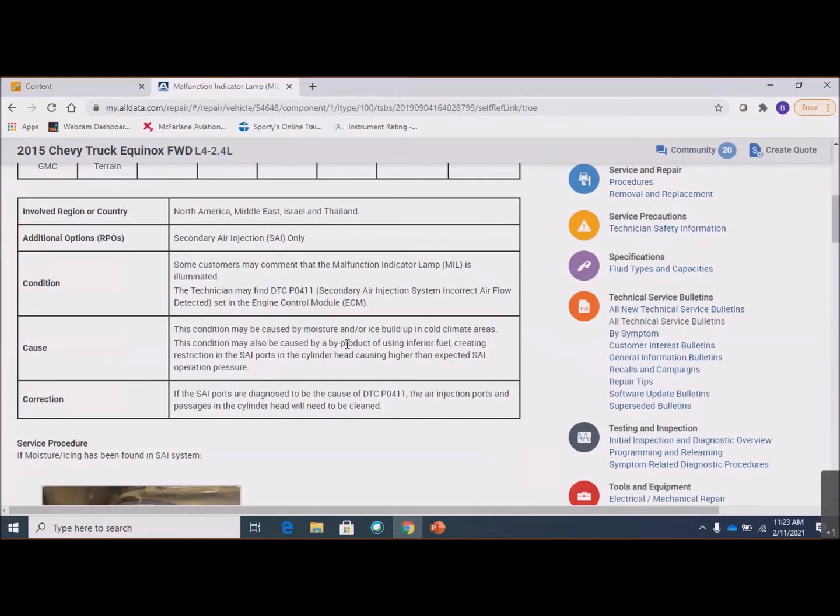If it were me, if I wanted to test the operation, the flow of air into the exhaust, I would watch the oxygen sensor, kick the pump on, and expect to see it go lean as all that air blows in. I have no idea whether that is involved in the diagnostics. I'm just saying I've seen things like that before.